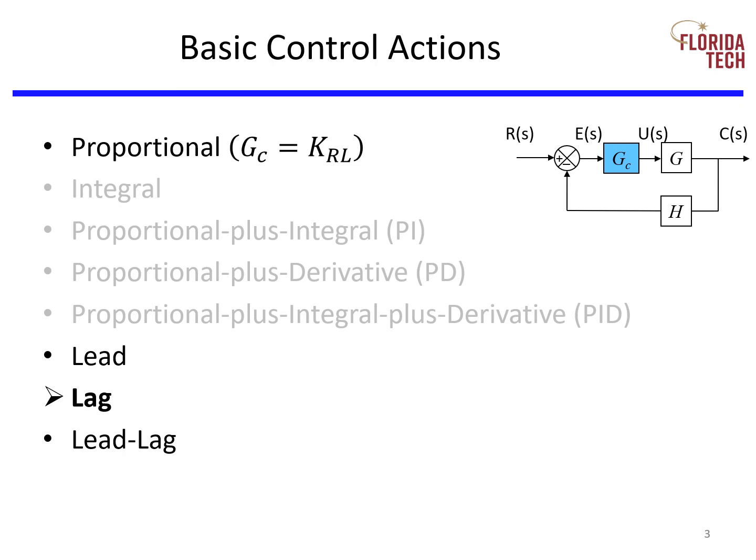We started with the simplest form, making the control a constant number. The root locus showed us all the possible damping ratios and natural frequencies achievable using a constant number, also known as a gain. We mentioned integral, PI, PD, and PID controllers, but we're choosing to instead add pole zero pairs, neither of which are at the origin.